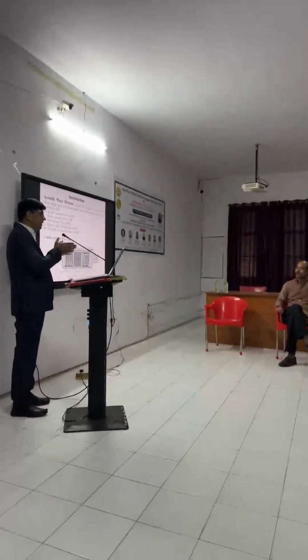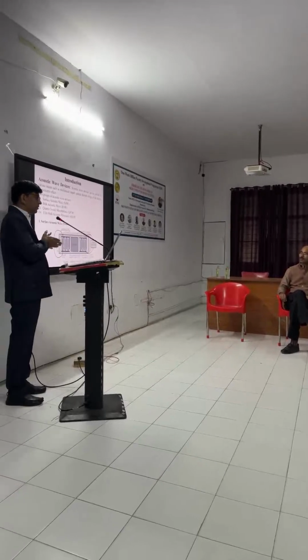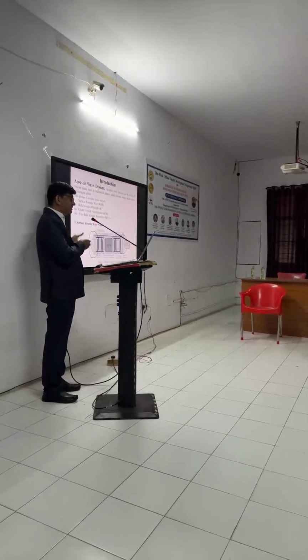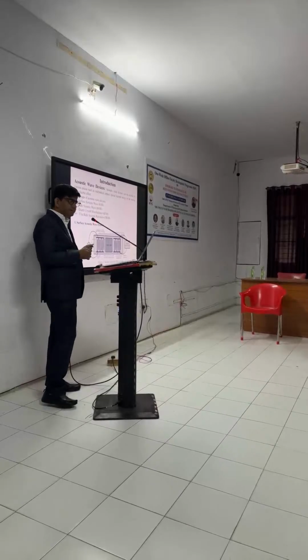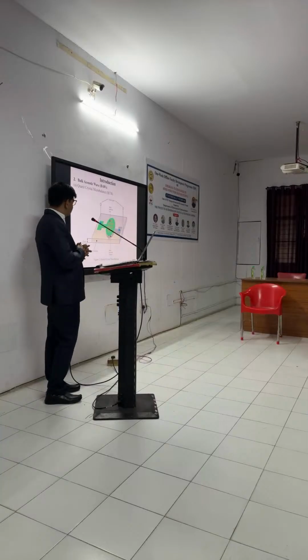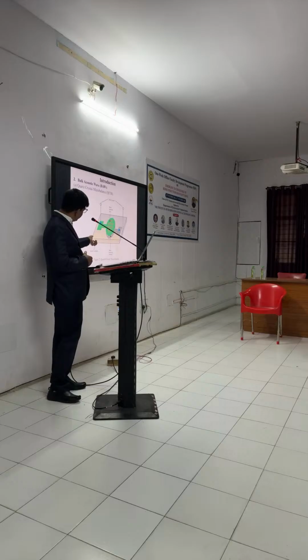Clear? So basically we measure the change in the frequency with the help of the presence of any kind of gases or physical quantity, pressure, it may be anything. Clear? Then next we have bulk acoustic devices. In these bulk acoustic devices, instead of an interdigital transducer, we have a piezoelectric substrate, and on the bottom side and top side we have an electrode.